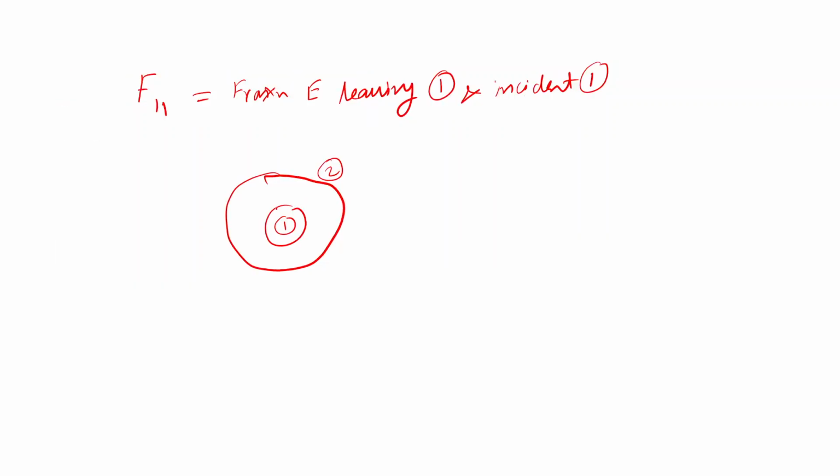And here the outside part was reflecting. So if I just consider my first surface 1, this is my reflecting surface. If I have energy leaving 1, it won't ever come back to this surface again. So that is why we write F11 equal to 0.